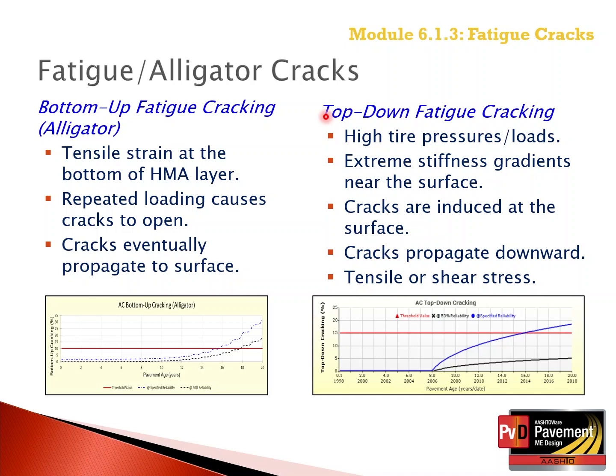It is difficult to determine if the alligator cracks are top-down or bottom-up cracking at the surface without the use of cores.